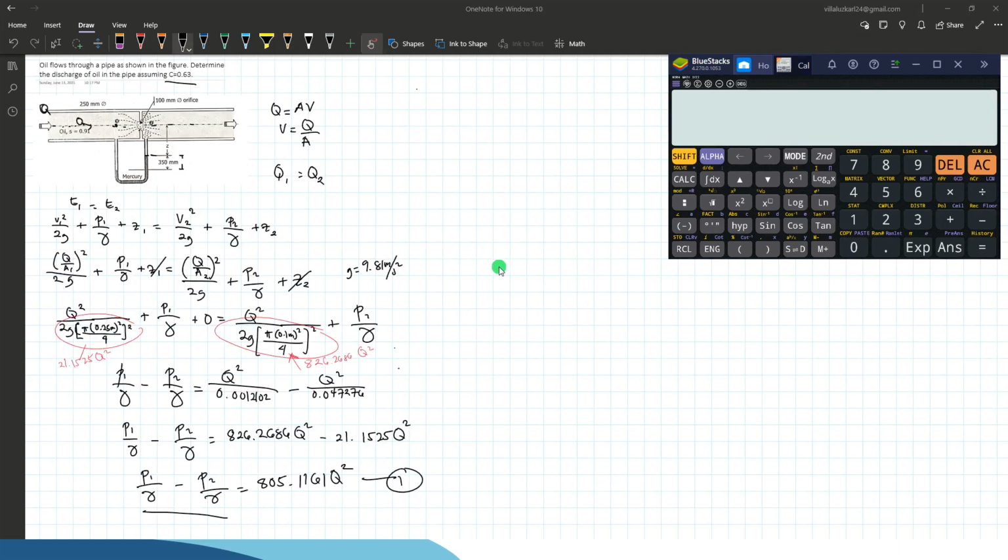So the next solution here now is to find this difference in pressure from point 1 and point 2. Using the same principle, the difference in pressure is equal to the sum of the unit weight of the fluid multiplied by H. In finding the difference in pressure from point 1 to point 2, what we only need to do is divide both sides by the unit weight.